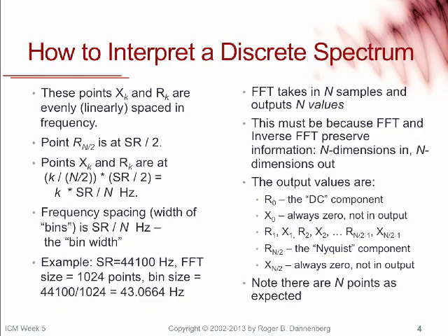If you look at what happens to a sine wave running at the Nyquist frequency, it starts at 0, the next 0 crossing is exactly at the next sample, and the next 0 crossing is at the next sample. So all the samples get multiplied by the 0 crossings, and they're all 0. So again, it's 0, and we ignore it.